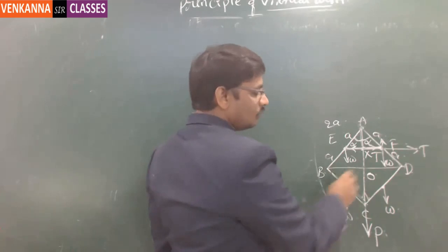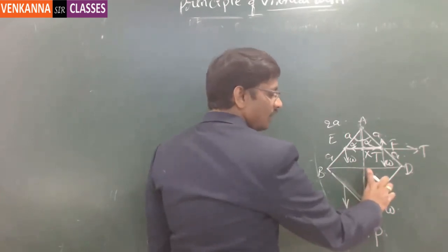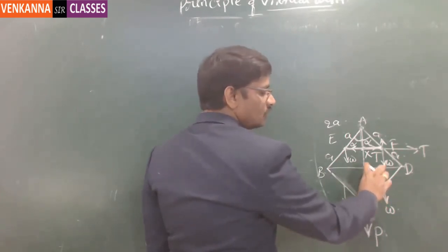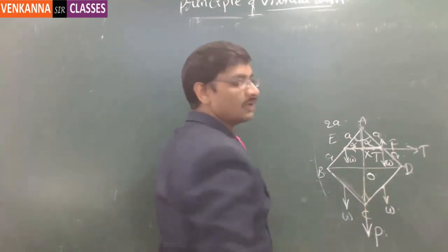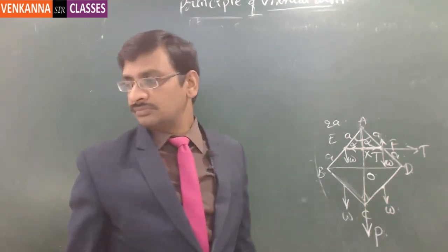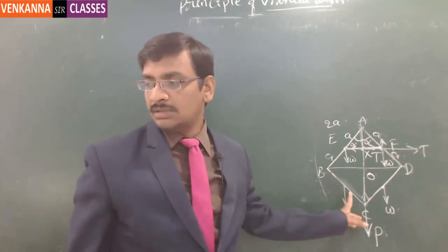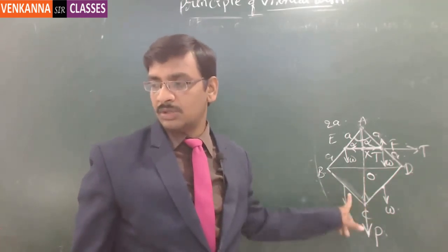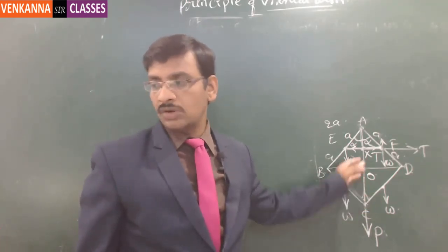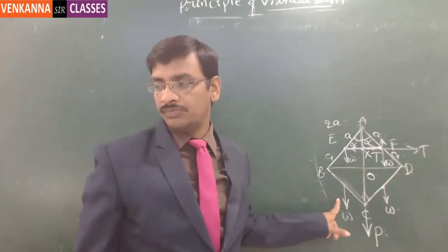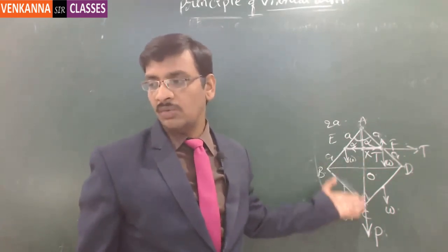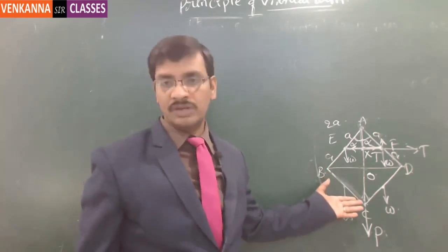That means if you notice, this vertical height whatever it is going to be there is going to be changed for this particular W. Got it or not? So this length projected onto this line, which is nothing but 2A cos alpha, is going to be changed for this particular W. Got it? Because there is only one vertical virtual displacement that we have given.